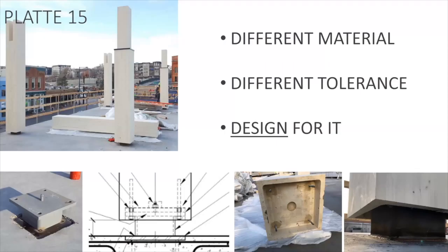Another kind of connection that's not so simple that I think is equally important is where we interface mass timber with other systems. I think that Chris brought this up. He actually had a category called adjacent structural systems. This is one of my obsessions because the concrete, in this case, the flat podium at plat 15, even when it's within spec, is plus or minus 3/4 of an inch, right?